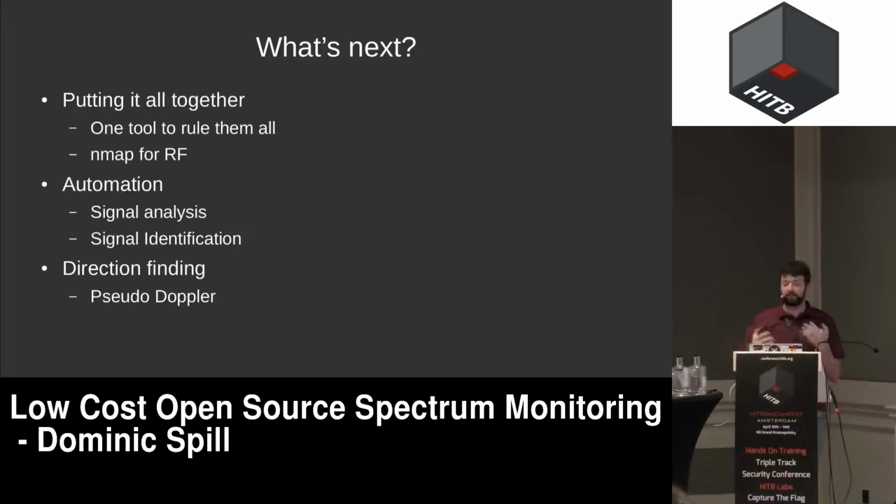And if we're able to synchronize the switching of the antennas with the dumping of the buffers back to the host, we'll be able to perform direction finding at the same time as sweeping that whole band. So while you'd lose some performance across the band, you'd be able to gain some information about the direction of the signal. So that is on our to-do list.